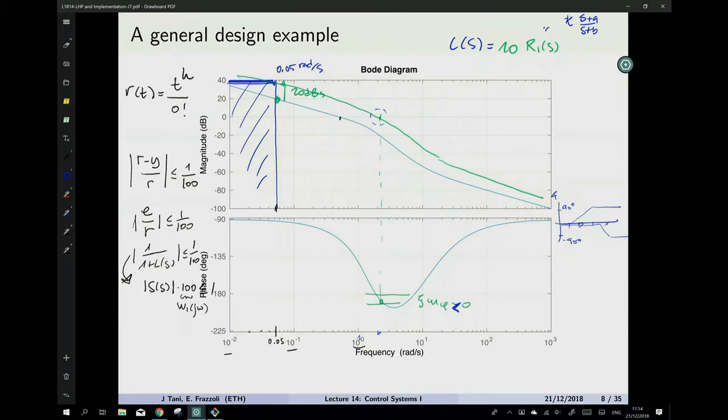Well, the square root of A times B has to be 2 radians. Yes. Okay, so A times B has to be 4. Why this? Because the peak of the phase contribution, which makes sense since we're designing a lead compensator to get the maximum phase contribution we can, is at the geometric center of where we put the pole and the zero. So the question is, where do we put the pole and the zero? And that is a function of how much phase increase we want.